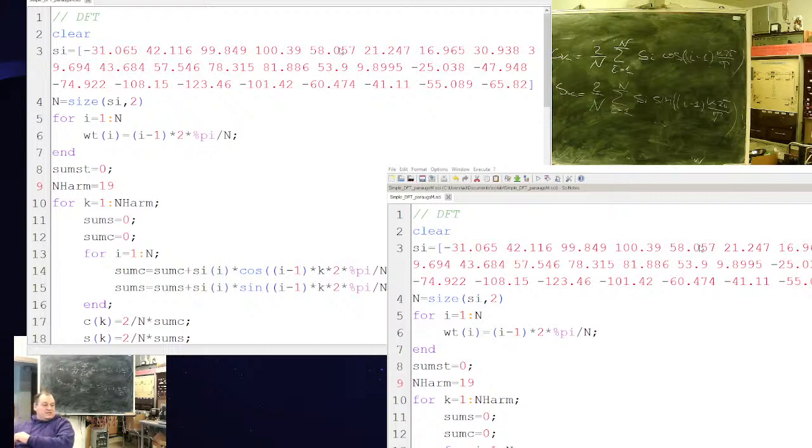It's the rule of the Nyquist frequency. To process a signal with frequency up to F max, you need to take samples with frequency double F max. If you do not do so, your sound will be distorted, your image will be crippled, your, I don't know, you can try to control your plane and your plane will crash. Because you will get this oscillating noise in your control channel. Everything will fail. It's what it tells you. It sends you a bottom line for your hardware performance.